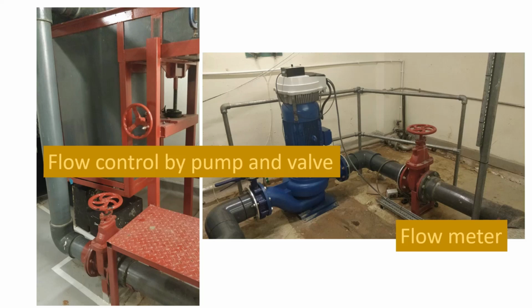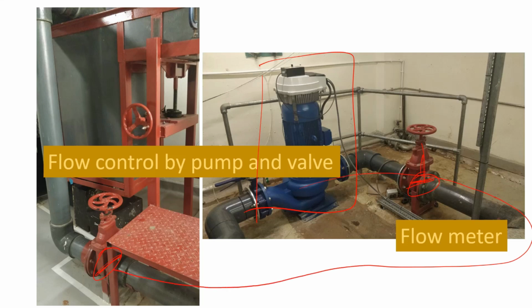The flow in the whole system is controlled by this pump. That sets a certain flow rate, but it's actually also adjusted by 2 valves. By changing these valves, if we can close this and close this valve, so the water goes from this pump along the pipes and eventually comes into the upstream end of the channel where it goes down here, and then it comes out at the end of the channel and eventually goes back into the pump. So it's a recirculating system.